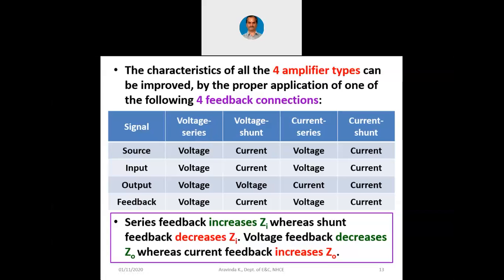Right? So that way, output voltage is taken, it is related to output only. So remember output impedance and remember reduction of output impedance. Now series connection is at the input only and it is related to input impedance. Remember it as input impedance and remember that input impedance is going to be increased.